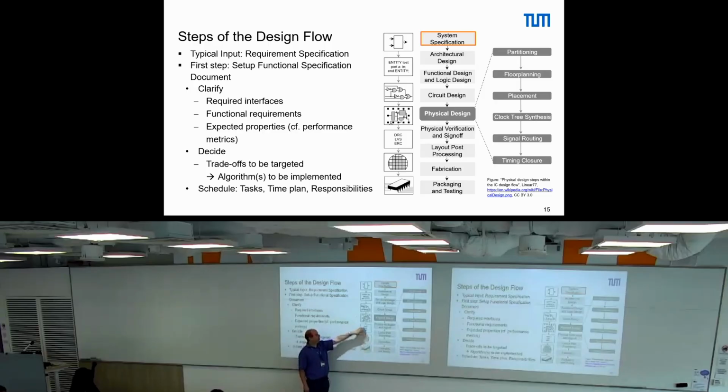So we have the different abstraction levels of our chip, different levels of description, which from the effectively physical device go higher and higher. So we have here a specific level, which is close already to the physical world. This is further away, further away, further away, and at the end, on the very top, we are at this block level where we start our design, right? So abstraction level effectively is about how to describe on this level our circuit.